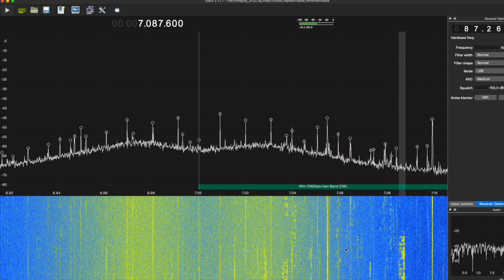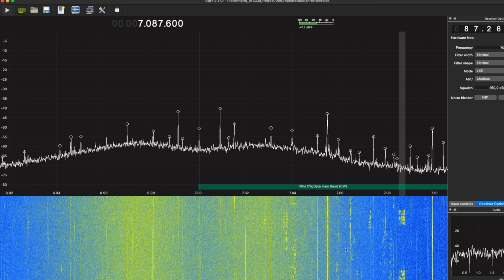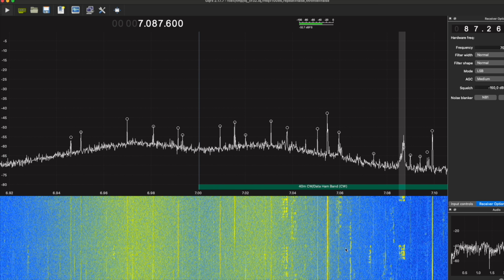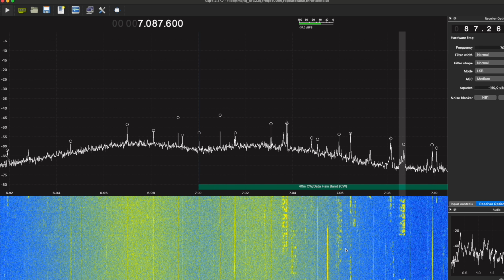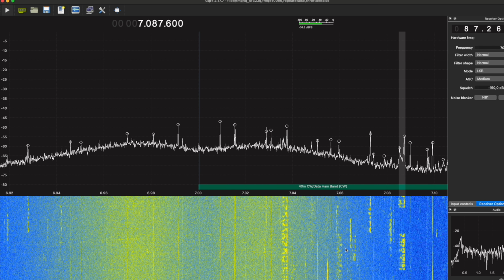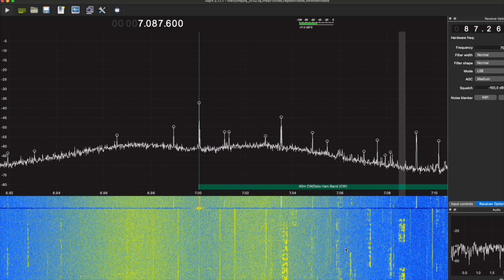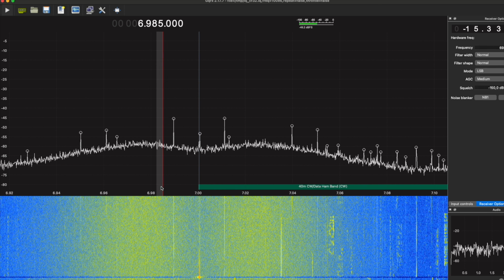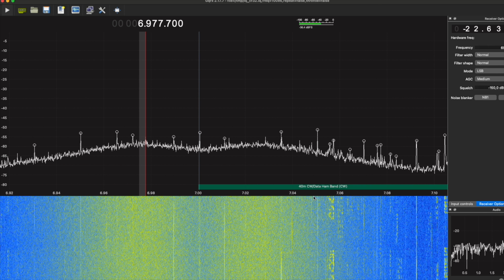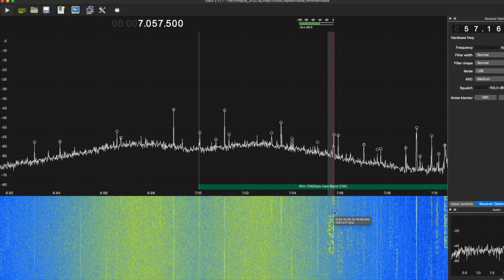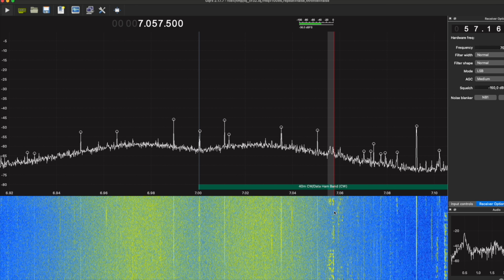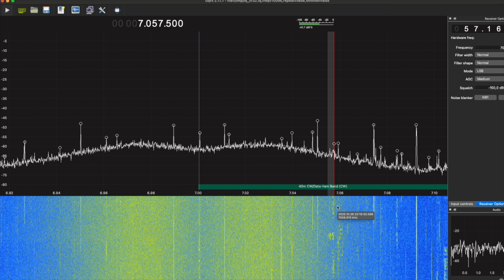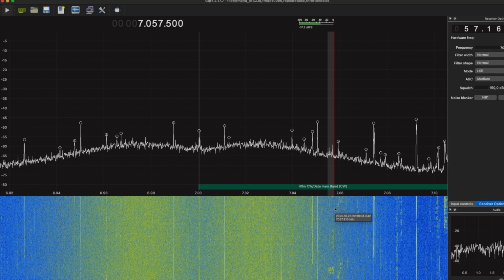And sure, it is nice to be able to cobble together a cheap shortwave receiver and receive a station at least 1,500 kilometers away, but I was still hoping for a flatter response, better image rejection ratio, and a cleaner spectrum. So I took it back to the lab, and when I measured completely clean IQ inputs to the ADC channels, I had to take a few days to think before I got some more progress.